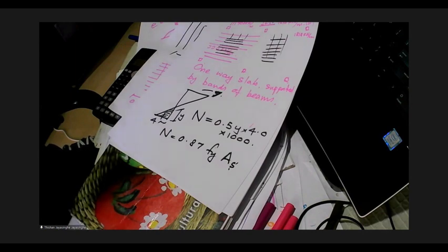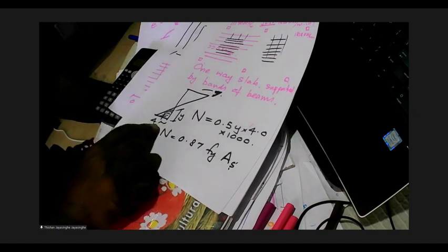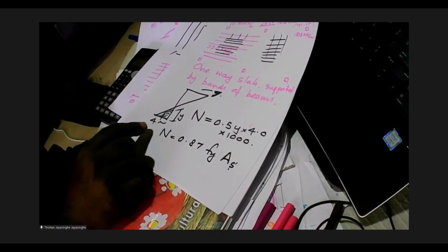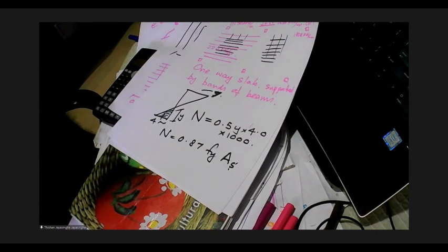The advantage is the slab will remain flat after tension, almost flat. And you can even balance up to 90%. So I started with 80% to ensure that nothing goes wrong. And then if these stresses are violated, then you can try 90% balancing. Balancing 90% of the dead weight also can be tried.